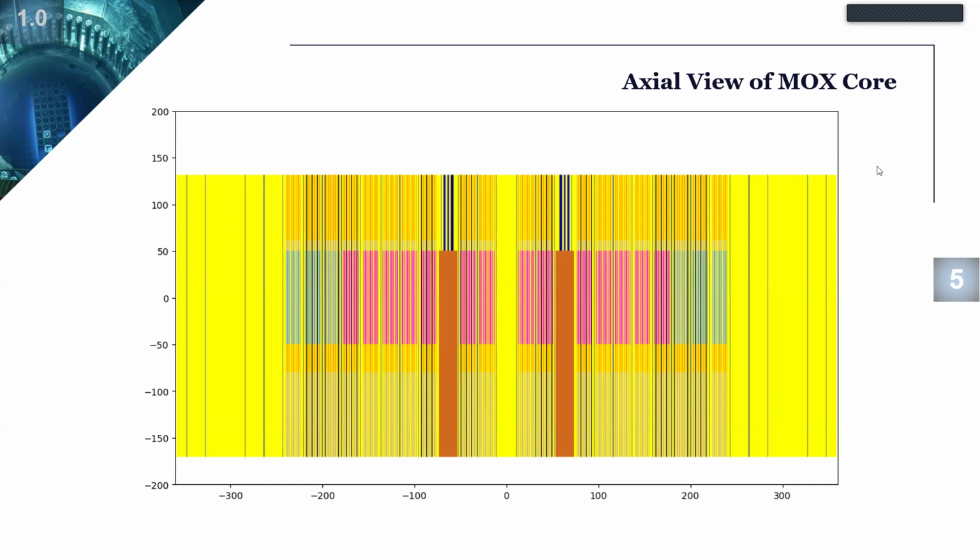But even before we go to that, for the CPS system, both for the diverse shutdown devices and the control shutdown devices, we also have the absorber material. There's a height constituting the absorber material that is approximately 70 centimeters plus 11 centimeters. You can see here. And then the rest of the height for the CPS system constitutes what we call a follower material, a mixture of sodium and ODS steel, in proportions of about 8% and 92%. Next slide, please.